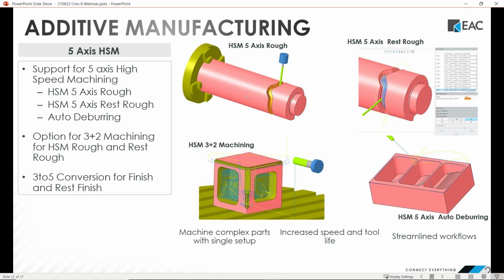And then additionally, there's also some conversion from 3D milling. You have a part fixtured, and it'll use 3-axis milling on that part. If it has some undercuts or has to use 5-axis, it'll switch to that, so you don't have to refixture or reorient your part. Again, you need a machine that can support that, obviously, but it can then switch to a 5-axis machine to finish up the part if it needs to. So it's a nice little transition to that.